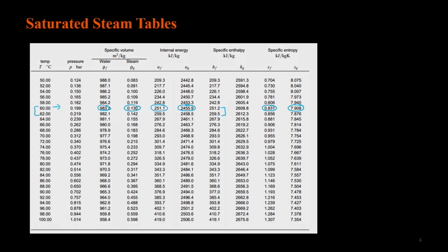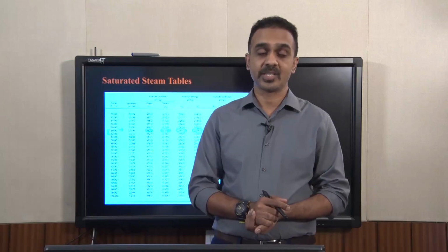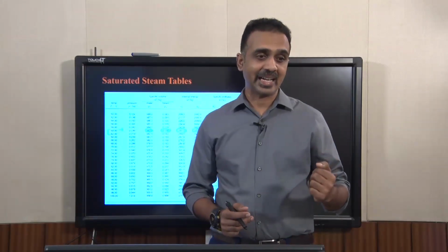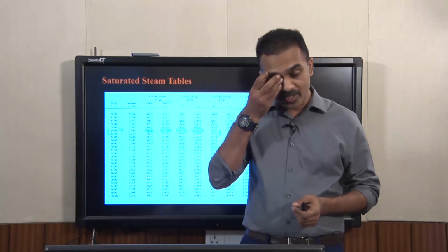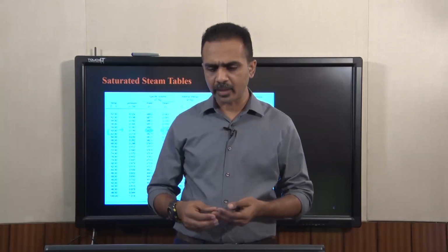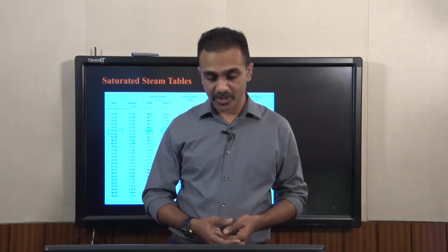The information that is stored in thermodynamic tables is similar to what is given in the form of thermodynamic diagrams. One of the more popular thermodynamic tables is what are known as steam tables. This is of course for water. There are two types of steam tables, one corresponding to what is known as the saturated steam, indicating that we have both liquid and vapor phases coexisting with one another at equilibrium. And then thermodynamic properties such as internal energy, enthalpy, entropy, density or volume, etc. are listed for saturated steam.